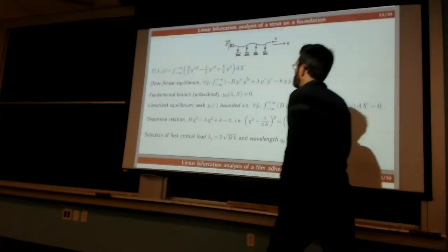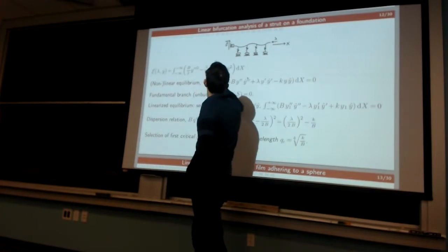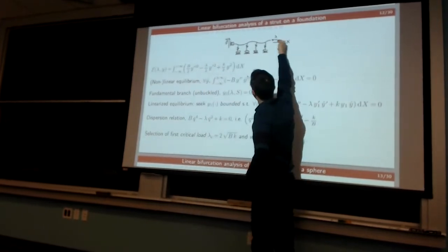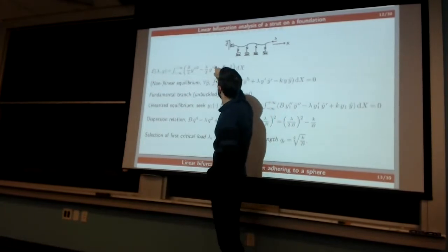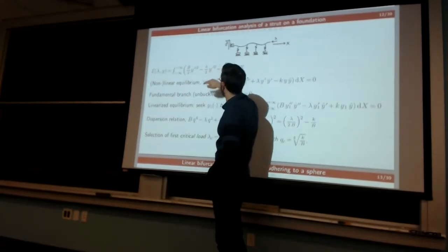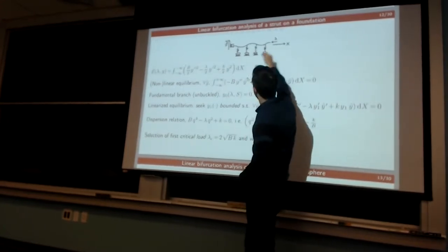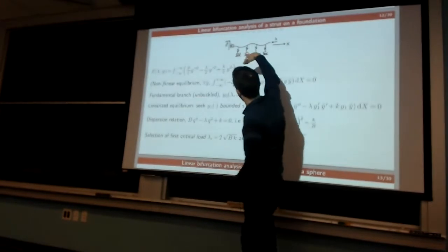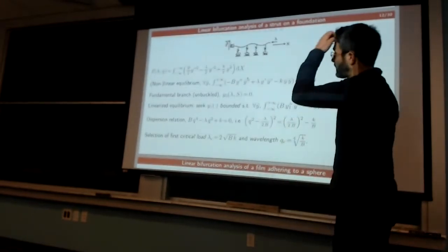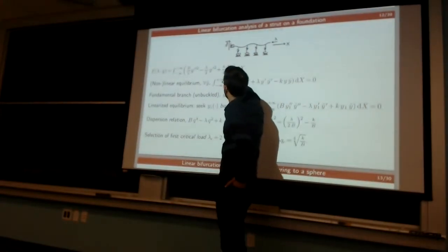Then the energy of the system would be like this, right? There's a bending term, and a term that captures the stress which is applied here, which tends to induce slopes. When lambda is compressive, the preferred configurations are those that are tilted. It's a classical effect of pre-stress, and then we have this elasticity term coming from the substrate.